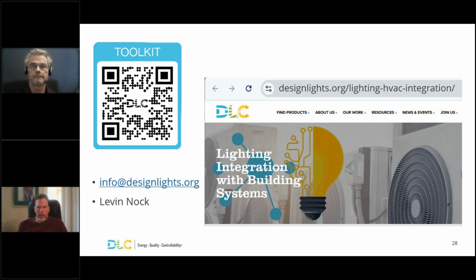CO2 sensors do that as well. That's the typical way the HVAC world works, using CO2 sensors. When there's more CO2 in the room, you know you've got more people, more bodies in the room. But one other thing that's really interesting about having a large density of occupancy sensors is you can use that to do traffic patterns. So you can know where people are in a space, what direction they're moving in, and how long they're in a space. That's good for other things, maybe other than just pure HVAC, but there's some good value in that as well.